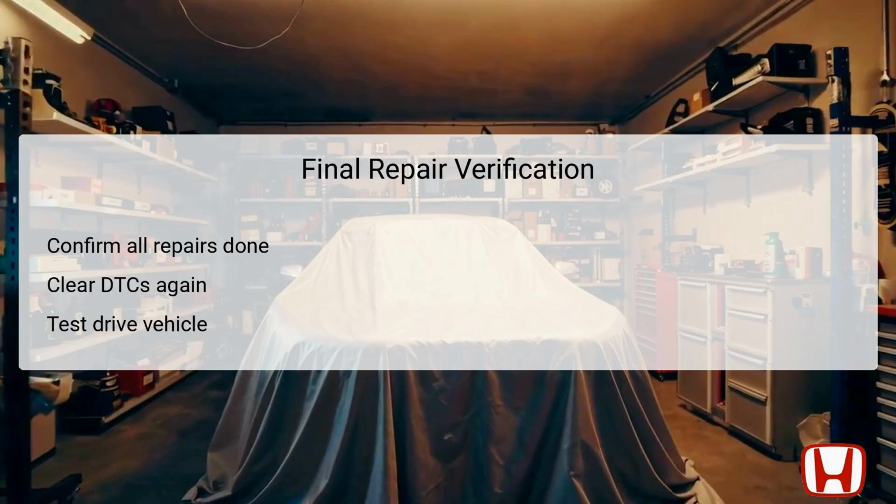Final repair verification is a crucial step in the diagnostic process. After taking the necessary repairs, ensure that all work is confirmed thoroughly, guaranteeing connections are secure and wiring integrity is restored. Clear any diagnostic trouble codes, DTCs, once more, using the Honda Diagnostic System to reset the PCM's memory. This step is key to check whether the P0202 code reappears.